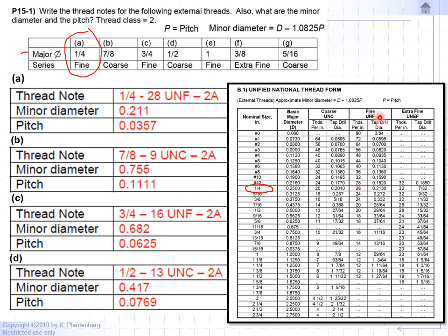When you're dealing with a bolt that's going to go through a lot of stress, especially a bolt attached to a moving part, like the internal parts of an engine or your wheel, fine thread is used. If you ever have to replace the rim on your car, the studs where the wheel mounts use fine thread.